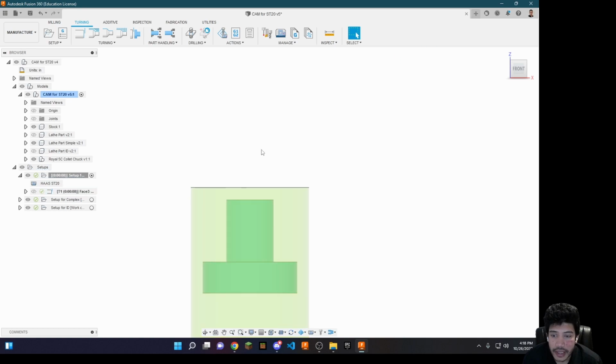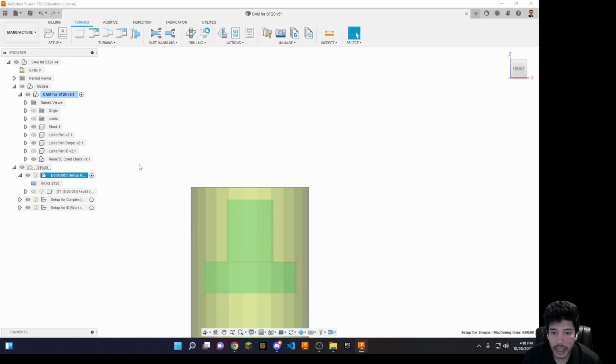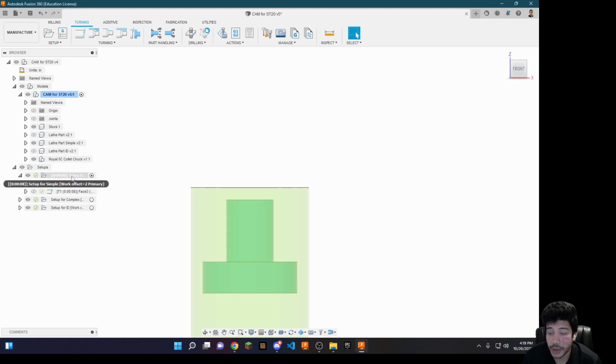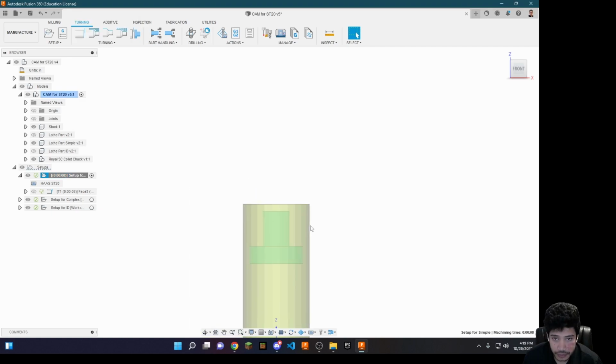And our facing is done. Now it's advantageous to try to use the same tool in your subsequent operations. That minimizes the number of different tools you need in order to achieve your CAM and will result in less time spent in front of the machine. The next operation, I'm going to cut out this profile.